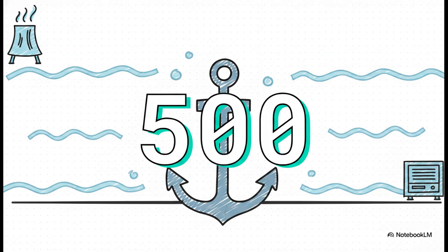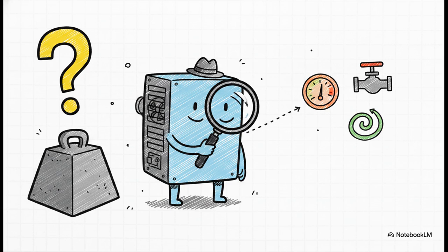We're locking this down so we can observe exactly how temperature differences and water flow interact without the distraction of a fluctuating building load. Now, you might be wondering how the equipment actually sees this. Here's a kind of wild truth about real-world operations. The chiller doesn't inherently know that the building load is 500 tons. There's no magic dial telling it the overall tonnage.